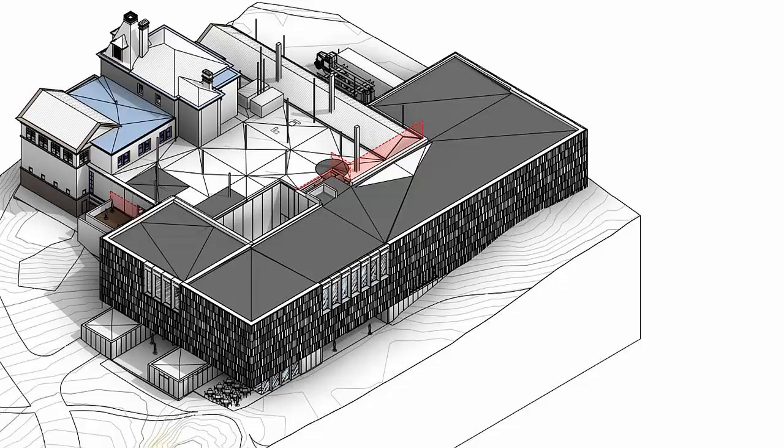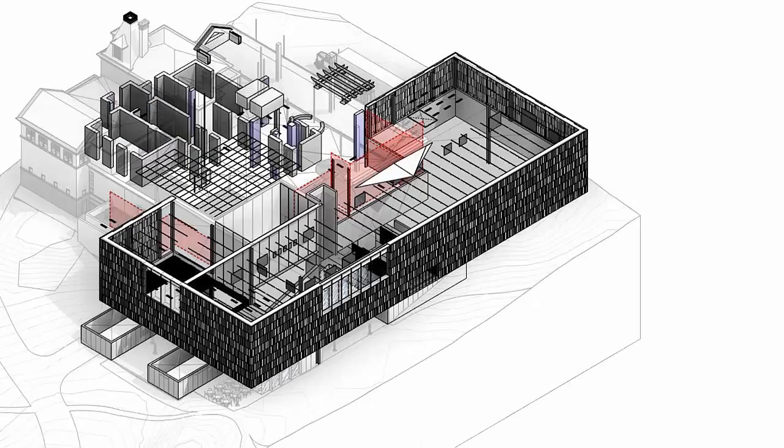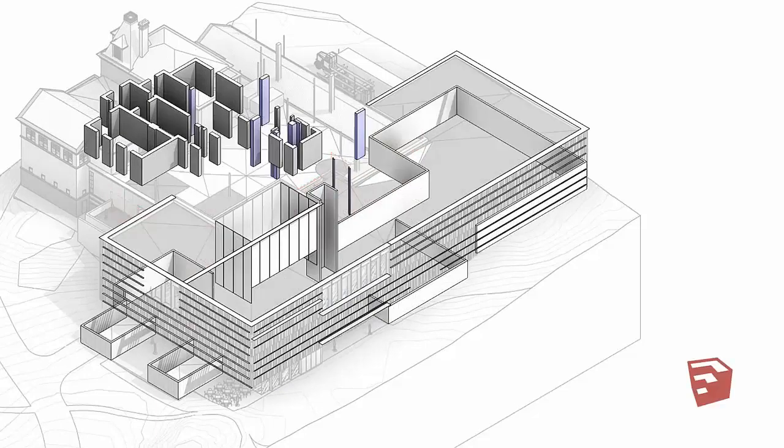And so SketchUp syndrome, this is a good example of in-place masses, and this has nothing to do with the architect or the design team. They're actually pretty good, and I like working with them. The model's actually not bad, but there are some examples inside of generic models. If I isolate what's called the generic model category, this is what you see. And then if I isolate the in-place masses, this is what you see.